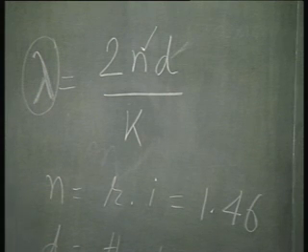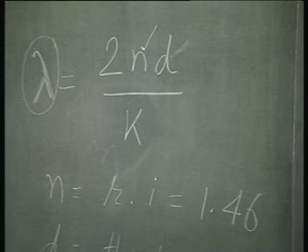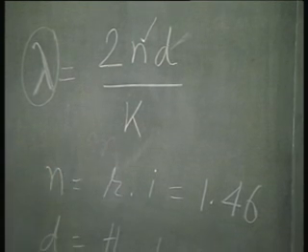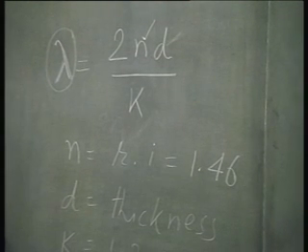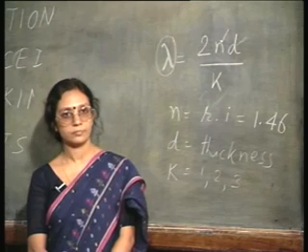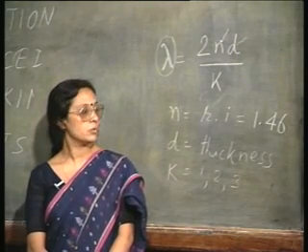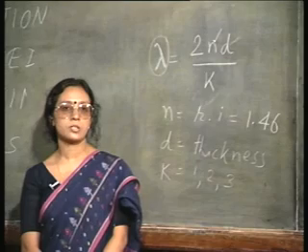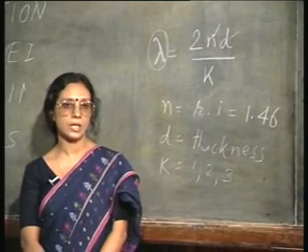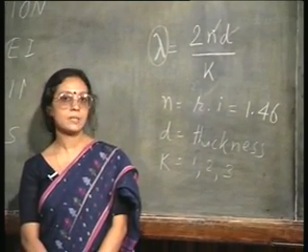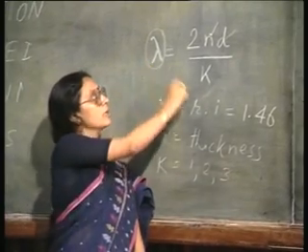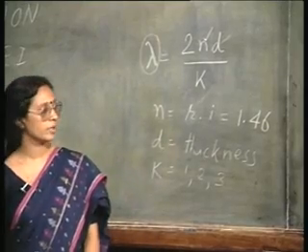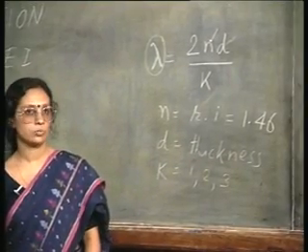one can evaluate the thickness. There is only one problem, that is depending on the value of K, we will have a repetition in the film color. So, you may have blue colored oxide film for more than one thickness. Only one thing you need to know: since you know the oxidation process time and temperature, you can estimate what is the expected oxide thickness, and then comparing with the color chart, one can find out what the actual thickness is going to be.